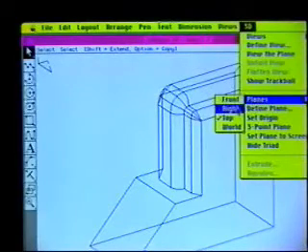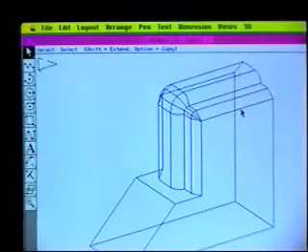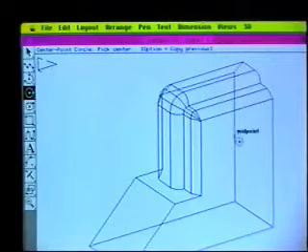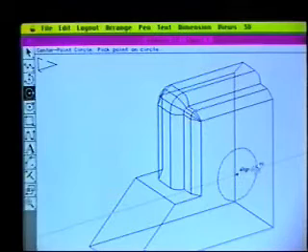Now right now I can see that the top is the active plane, so what I need to do is change it to right. And notice that my triad has changed to indicate that the work plane is now with the proper orientation. So I pick the circle tool, and I come over, and because of the drafting assistant I can find the midpoint, and I get a construction line off of that, and I'm going to find a midpoint along this face, and there's a construction, and there's an intersect of those two midpoints, and then I can just pull a circle right on that face.